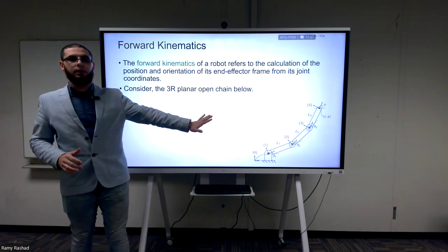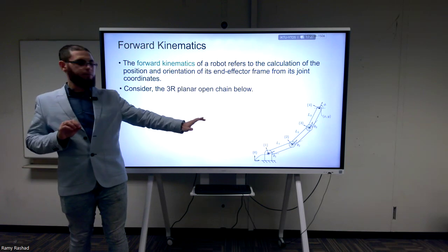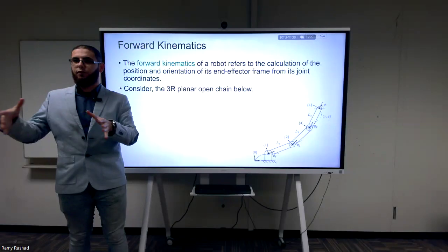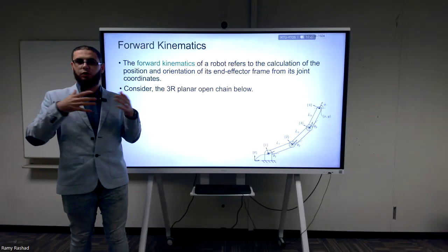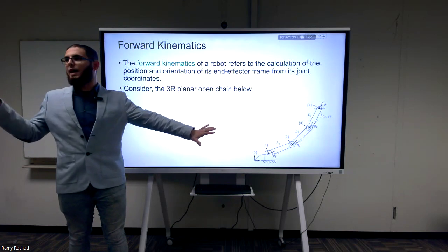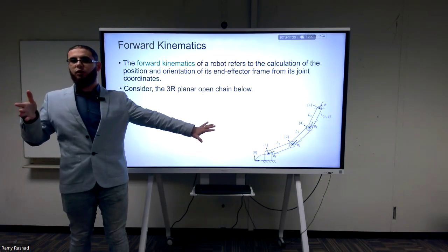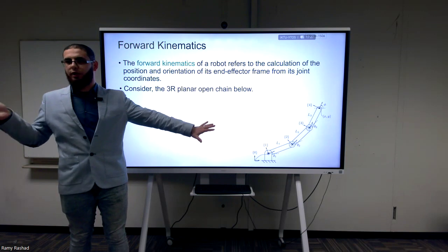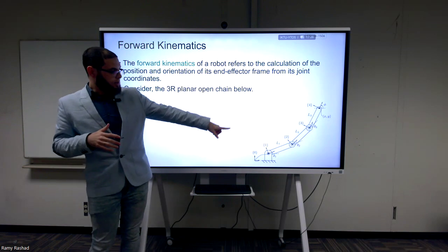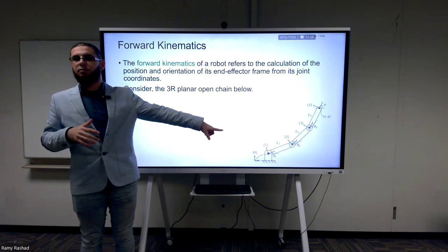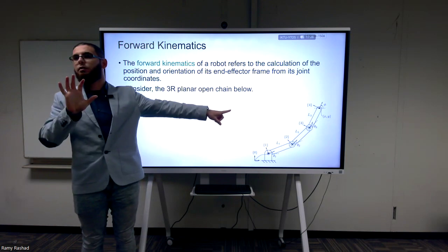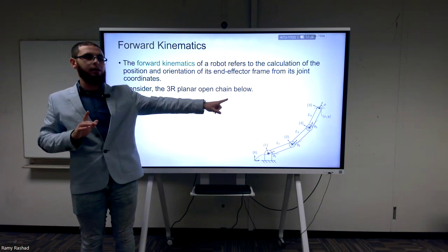As a side remark, even though we can do SO2 and SE2 and write the algebras in 2 dimensions, it's much easier to stay with the SO3 and SE3 that we learned, without introducing any more notation or new operations. Because what is the rotation here about which axis? If the motion of the end effector is in X and Y, moving in the plane, what about the angle or the angular velocity?